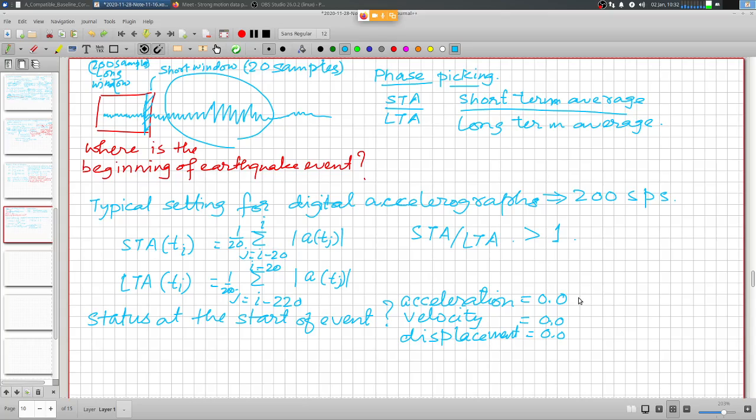Every measuring instrument has a least count, and so does our accelerograph. And that's where the digitizer resolution comes into the picture. Most of the accelerographs that we have have 16-bit resolution. In modern times we are beginning to get 18-bit resolution accelerographs. But whatever the resolution, there is a finite quantization. There is a least count below which the sensor, or the recorder, I mean your measurement system, cannot have any record.